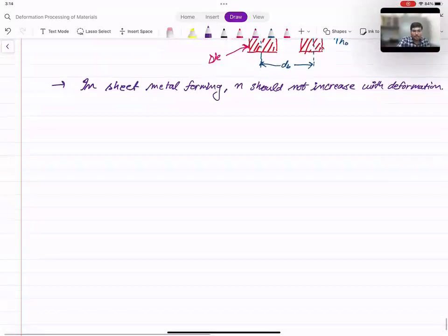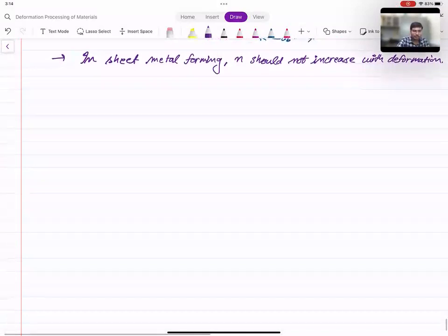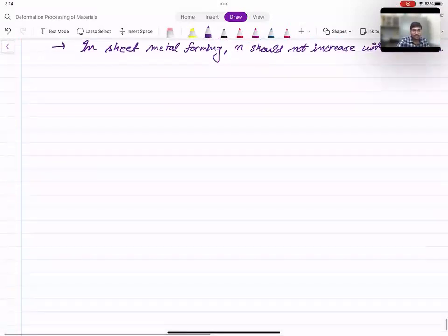Also, in case of rolling, extrusion, etc., in hot working condition, the recrystallized microstructure is obtained in the product. But in case of this drawing operation, it is generally done as cold working, so that phenomenon is not generally observed. Recrystallized microstructure is generally not seen here. Also, there is a contribution of roughness parameter.